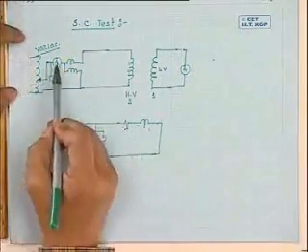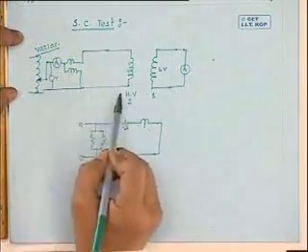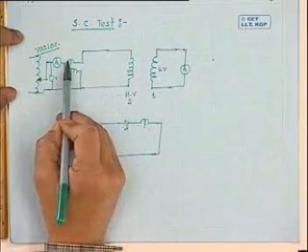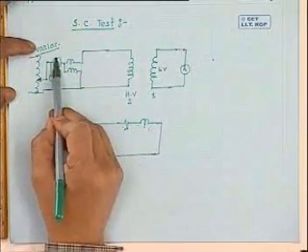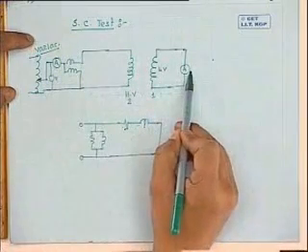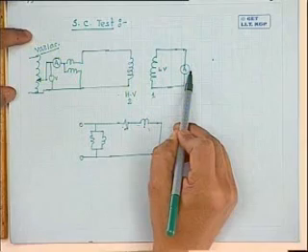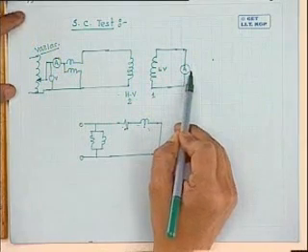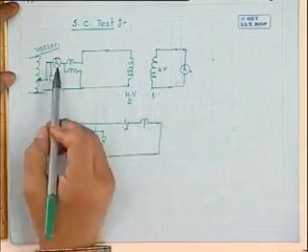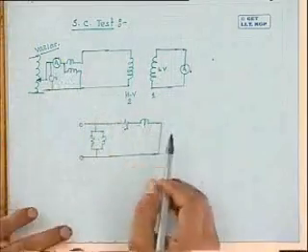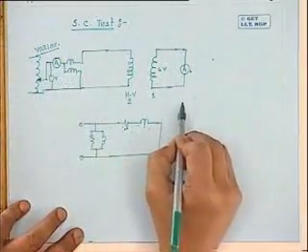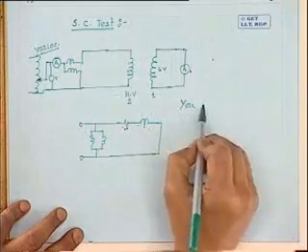So, go on increasing the variac setting such that rated current of this HV side now starts flowing. And you will find when this current is rated, the current in this one will be automatically rated by the transformation ratio of turns.